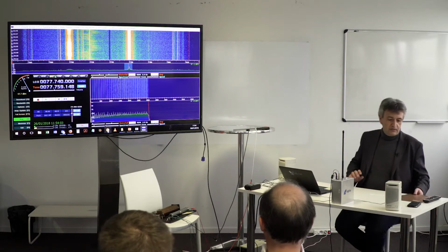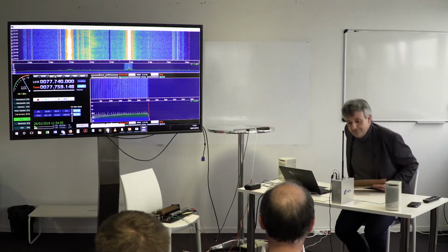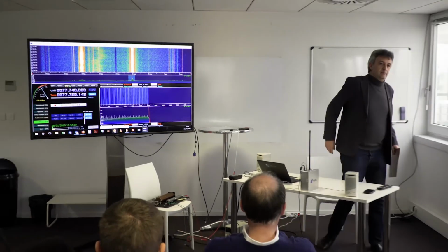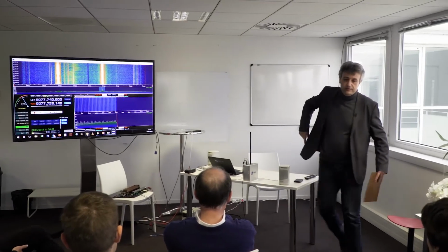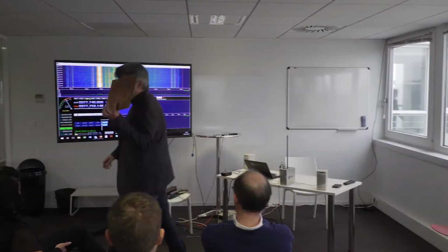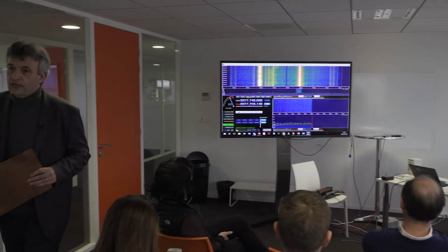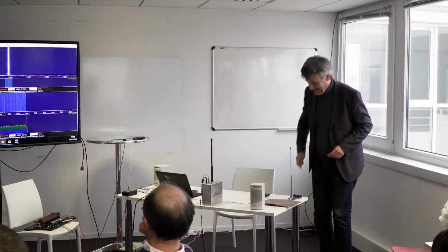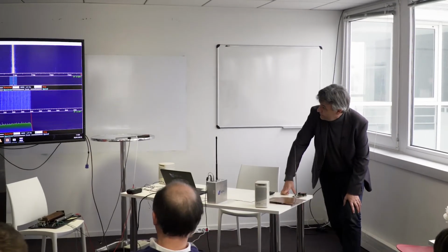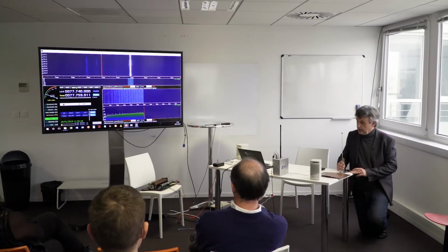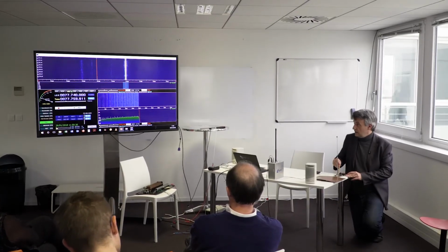What else can we do? Yes, it's maybe going to be a little bit difficult, and maybe I have to go back here, reducing the power. Now we are going to look at the influence of the environment. With a certain length of antenna, I'm going to try to find my maximum. So I'm looking at the RSSI monitoring device.